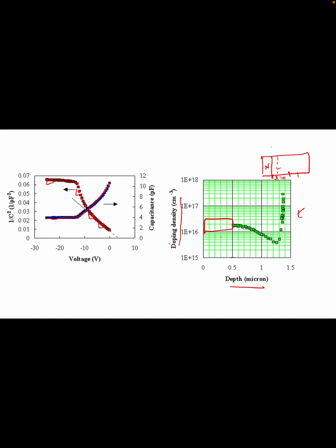You typically do not get information about the heavily doped region for a distance L_D. L_D, as we previously saw, is called the Debye length, because the actual potential is screened within the region of this L_D. So if the potential applied is such that the depletion width is close to this L_D, you will not see a lot of information here, because it is less than the Debye length.